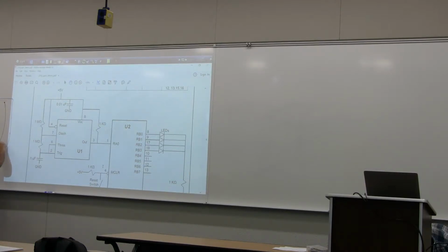Connect your blue lines together, connect your red lines together. And I do that regardless of what it is I'm about to wire. Why? Because now I've got 5 volts and ground on both sides of my board. And anytime I want to connect to VCC or ground, I can just run a little wire to one of those rails, and I don't have to cut across the board.